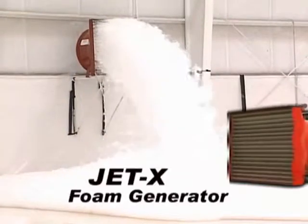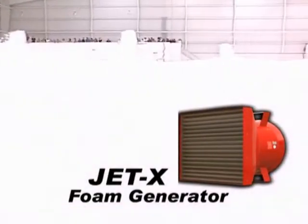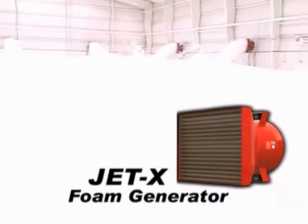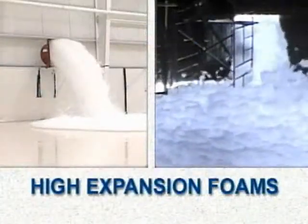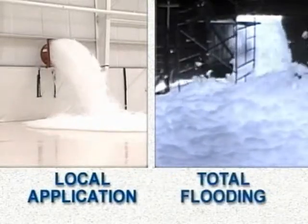Just one JetX 15 foam generator can produce a volume of expanded foam at a rate of nearly 20,000 cubic feet per minute, depending on inlet pressure. While most foams can only be used for two-dimensional hazards, the high-volume output of high-expansion foam systems enable both local application and total flooding protection.